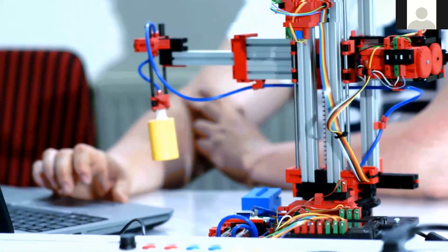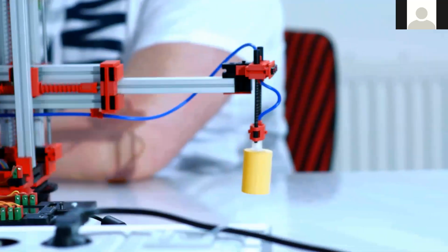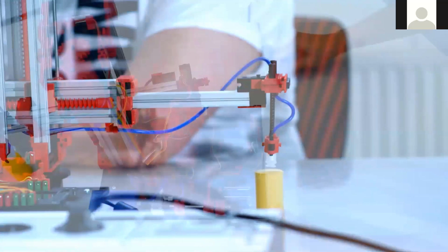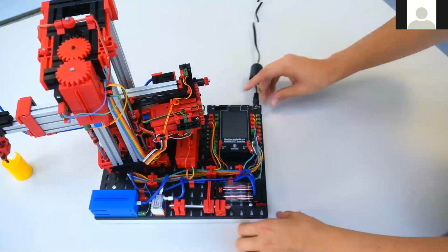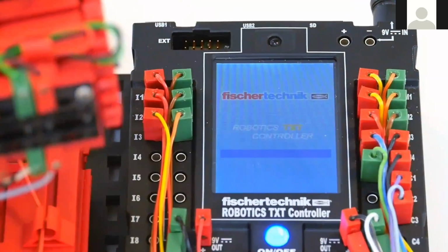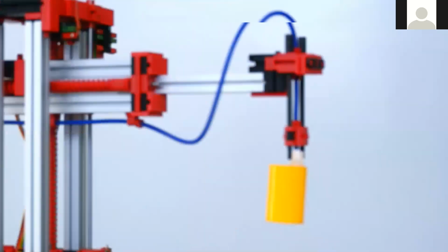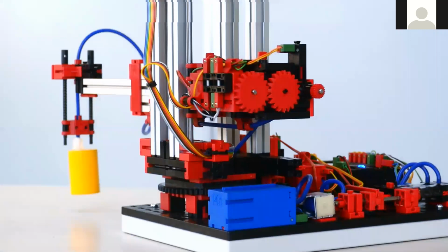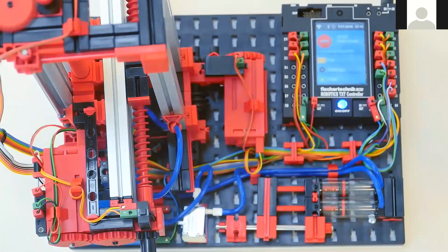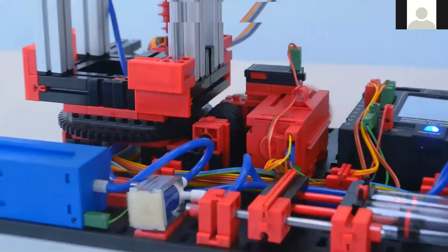The model includes 3 encoder motors, 3 push-button limit switches, a vacuum suction device, a compressor, which is the blue brick component you'll see in the video, and a solenoid valve. The model's dimensions are approximately 9 by 19 by 15 inches, and it has a weight of about 7 pounds. The 24-volt versions of this model, as well as all of the first 5 24-volt models we'll look at today, each have a relay board for motor polarity reversal, and also both have a multi-pin connector with 34 pins with a grid of 2.54 millimeters, as well as additional PCB terminals with push-in connections for all inputs and outputs.